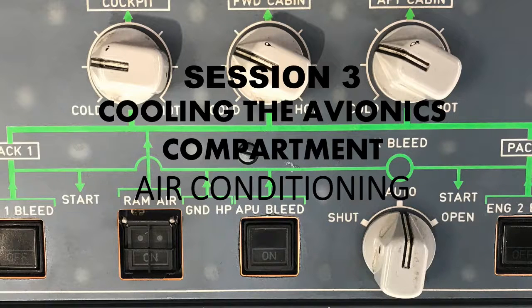And the outlet bypass valve, what's its job? It's going to let air into the system when the skin heat exchanger efficiency is degraded. So when you don't have that operating at optimal, that outlet bypass valve is going to allow air into the avionics compartment. The skin exchanger outlet bypass valve is located in the forward left-hand side of the avionics compartment, and both of them are accessible through the same door, just so you know.